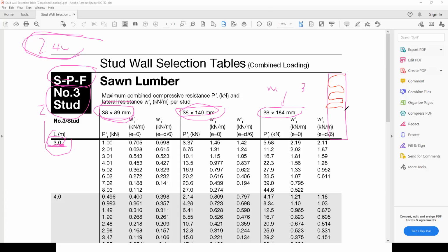So what's nice about using 2x6s is that if they're too strong, you space them further apart, you understand? And then you go up to 24 inches. And if they're still too strong, you don't care. They're going to be ample for your structure.